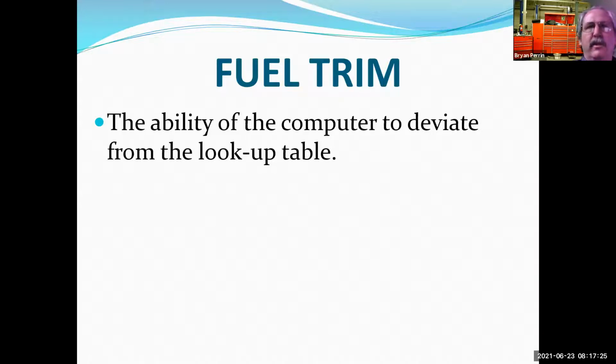And this car had already been to 2 shops that had parts put in it. And it's like, what the heck? The oxygen sensor is good. That's the eyes. The eyes are good, but yet the computer's taking away too much injector on time. And the car's running lean and failing for high NOx. So it was a bit of a conundrum, and I had to kind of get out of the box and